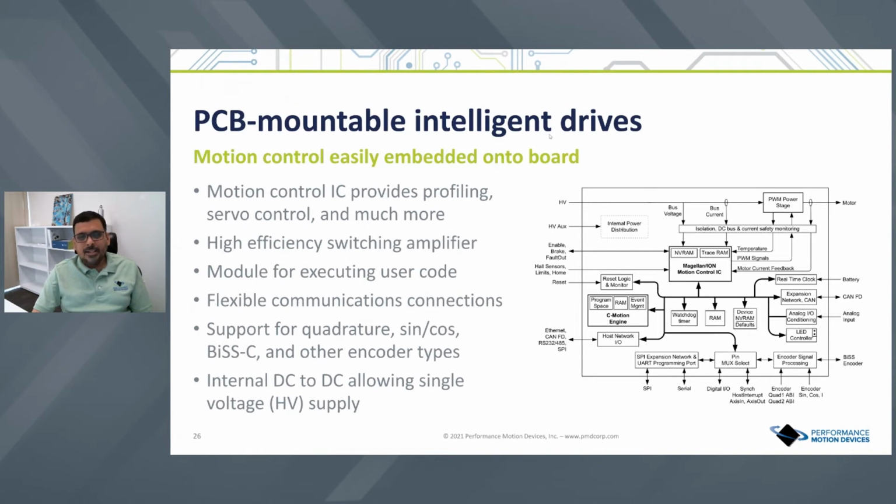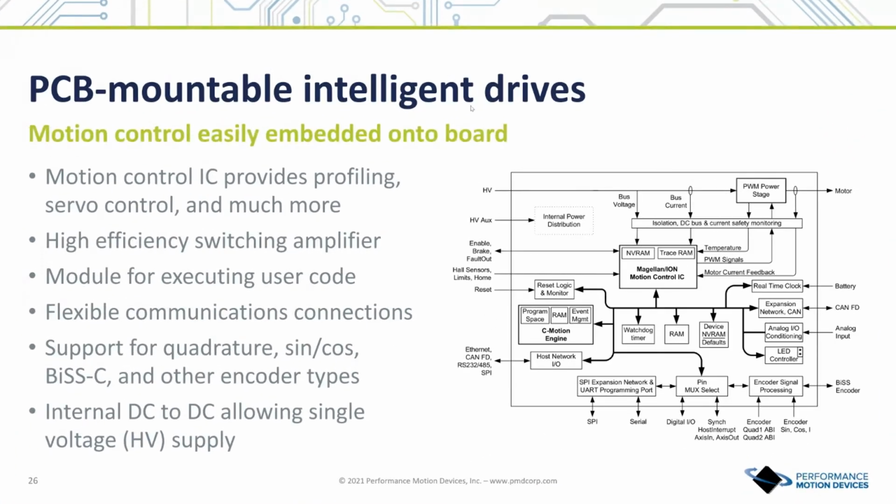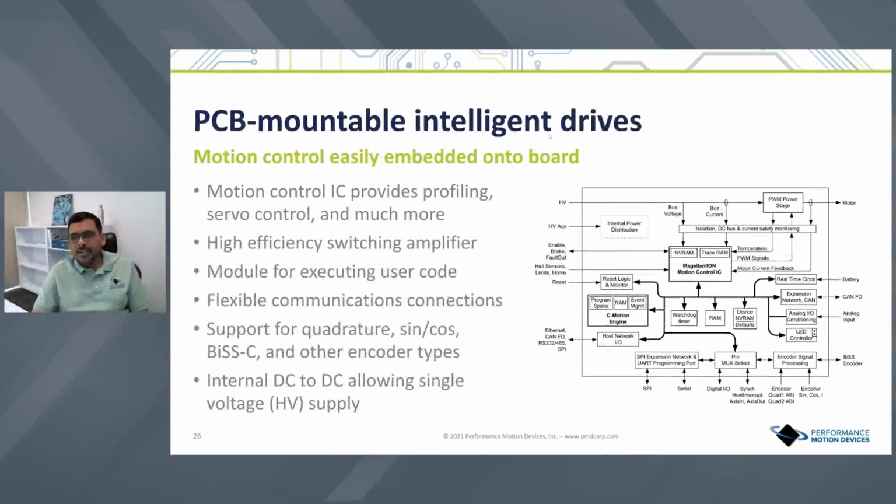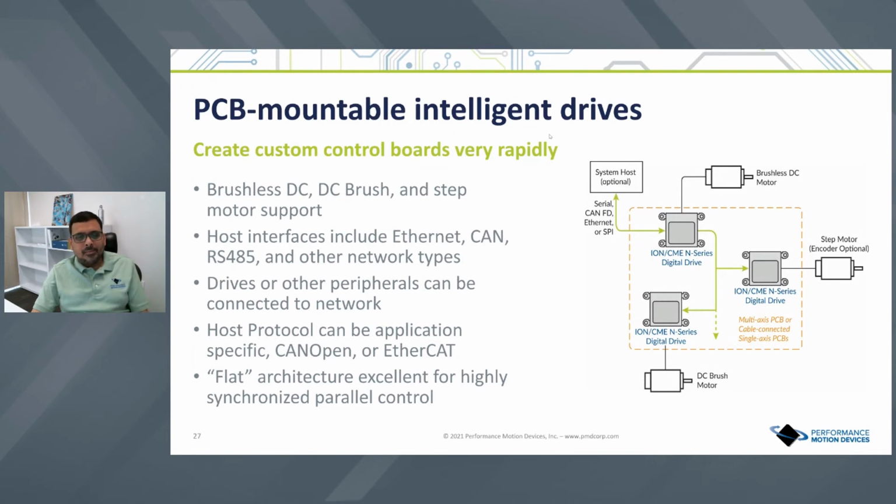So this is a little bit more detail on this drive. This obviously supports all of the things we talked about so far. It does the sine cosine encoder, it does high frequency PWM, and it supports a whole range of host interfaces. And obviously it does a bunch of the safety stuff, where in that case they need 2 separate power supplies. So you have the HV for the high voltage to drive the motor, and you have a separate HV aux supply to keep the controls alive and report back safety and status. And there's a lot that you could do. It has the C-Motion engine where the user can write code to run on the drive for safety or if they want to do a translation from their packet format to a PMD packet format. And we also support BiSS and some of the advanced encoder techniques here. So this is just a view of the capabilities you have.